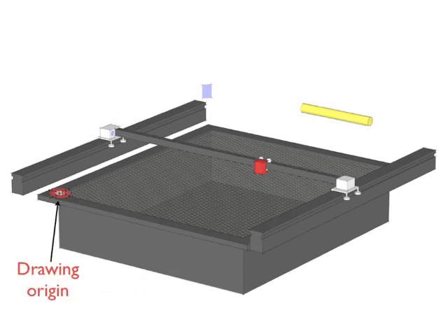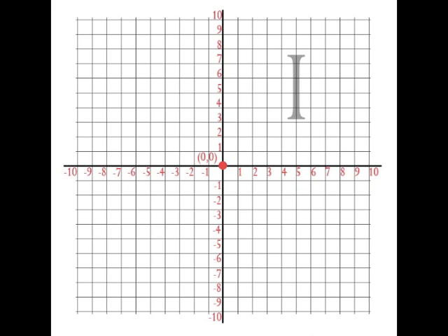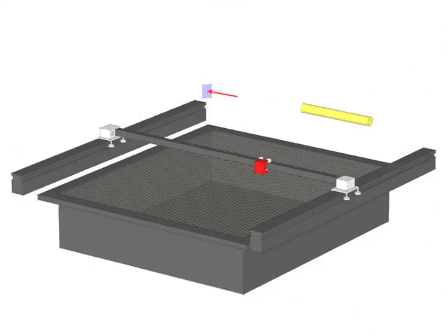The Cartesian coordinate system is used to map what is seen on the computer screen to the laser cutter bed. It is easiest to assume the drawing origin is at the lower left-hand corner of the laser cutter bed when facing the machine. The coordinates are 0, 0. This will come into play when we configure the printing properties. Once the machine is started, a continuous laser beam is reflected off the mirrors to burn the material. The cut produces a bright white light and, as a precaution, should not be stared into, for it can cause retinal damage.